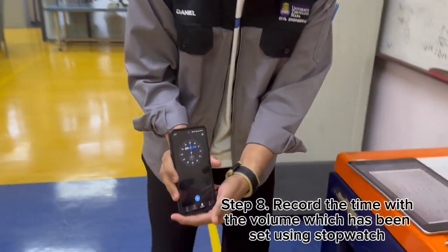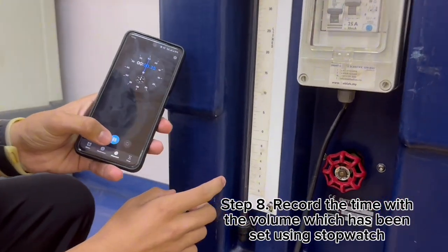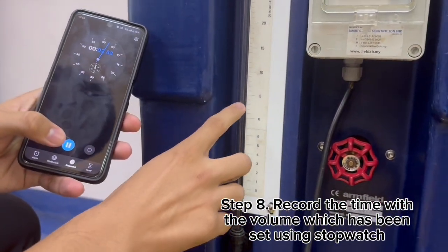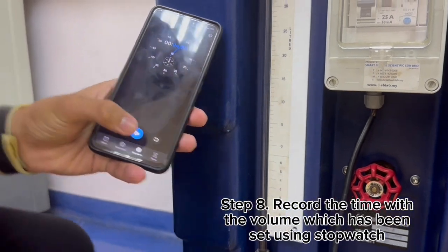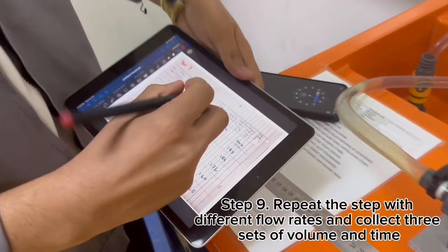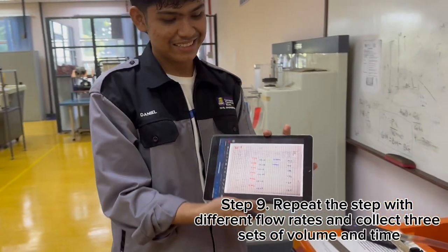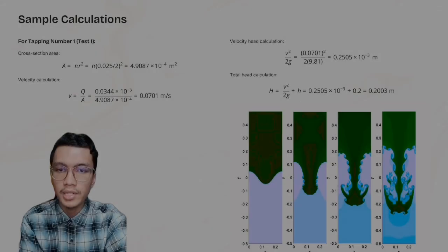After that, we need to record the time with the stopwatch. Using the stopwatch, you need to record the time for the volume that has been set. For example, the volume is 0.002 for the first set, and take the record into the table. After that, repeat the step with a different flow rate and collect 3 sets of volume and time readings to calculate the average flow rate.